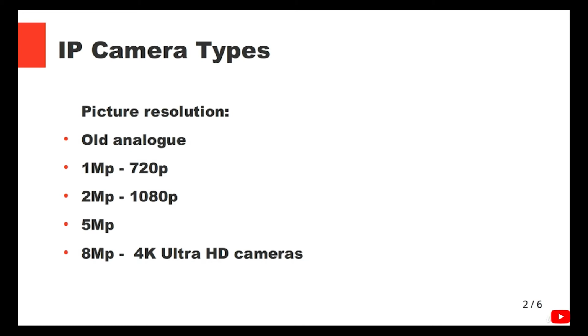Let's say you're planning to upgrade the NVR next year, so this year you're upgrading cameras. You can change the settings in the camera to the maximum that NVR can handle, which in that case would be 2 megapixels. And then when you upgrade your NVR, you can upgrade your cameras just by logging into them. So that's a good thing.